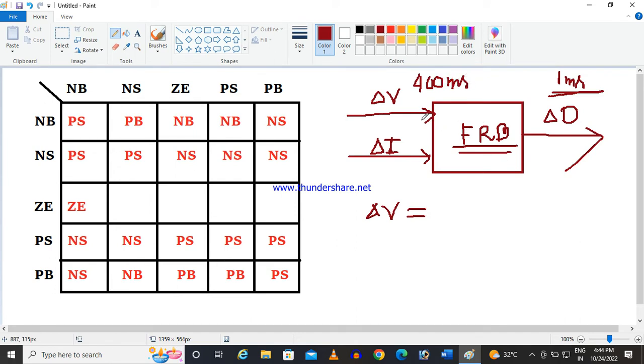After that it comes to the fuzzy calculation. In the fuzzy calculation, first it fuzzifies the physical quantity using the membership function I define. Then based on the fuzzy input and output variables and the rule base, it calculates the output, then defuzzifies. Say these things took some 200 milliseconds.